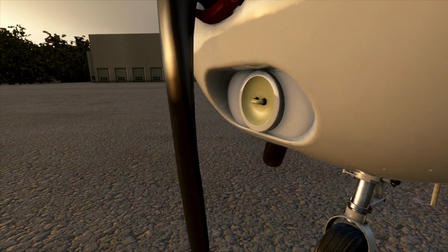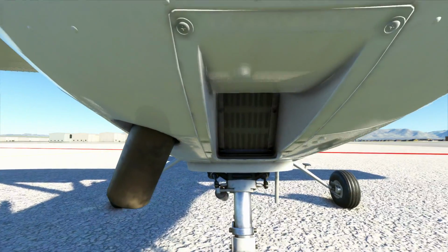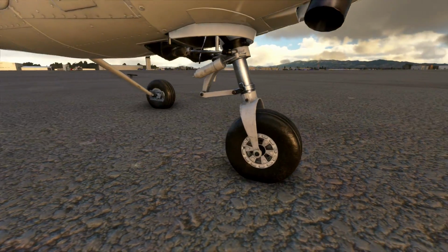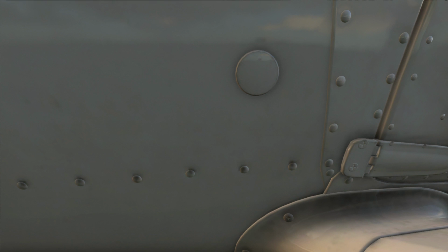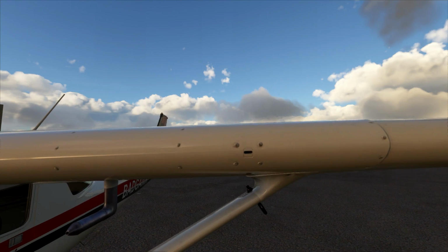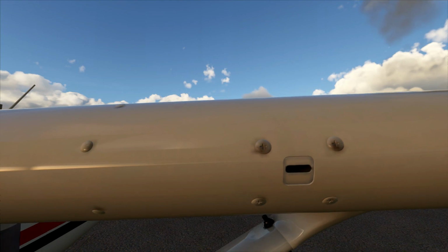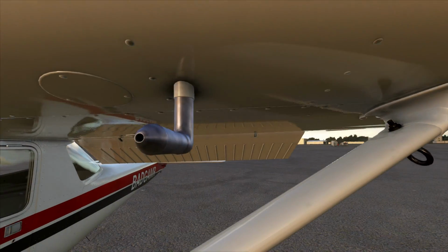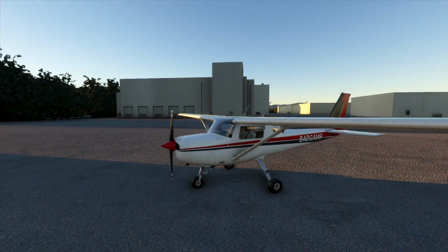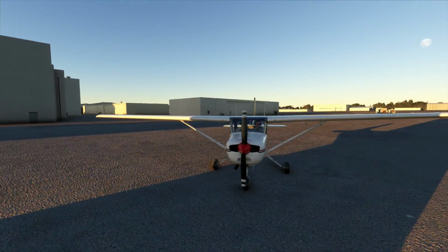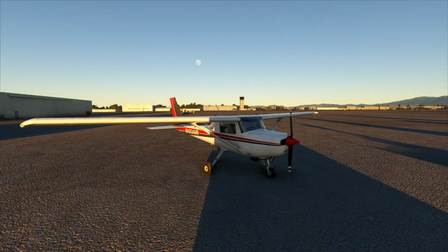The landing light is cleaned. The air filter is cleared of any obstructions. The nose wheel is inspected for wear and inflation, and finally a visual inspection of the static port on the side of the aircraft is carried out. The left wing gets the same treatment as the right, with the addition of an inspection of the stall horn and the pitot tube, not having any obstructions. The exterior pre-flight inspection is complete and the wheel chocks are removed in preparation for flight.